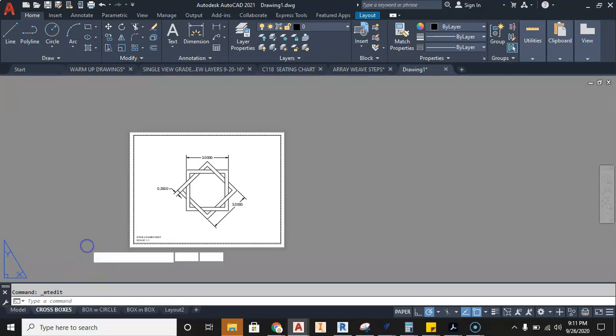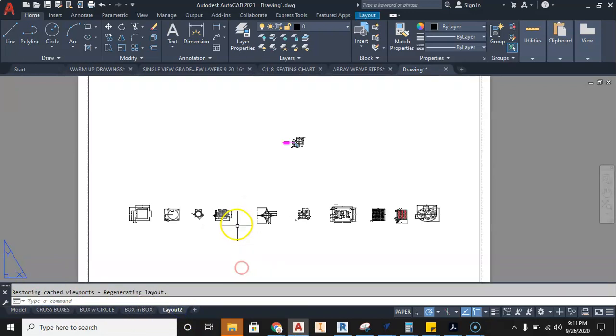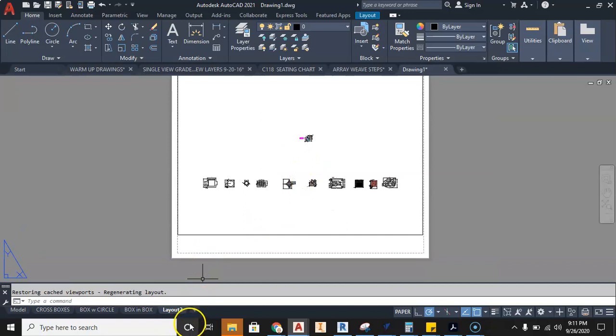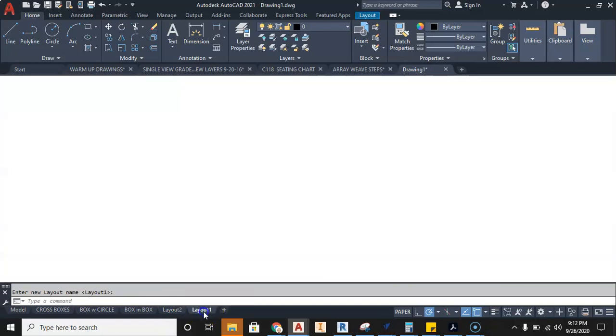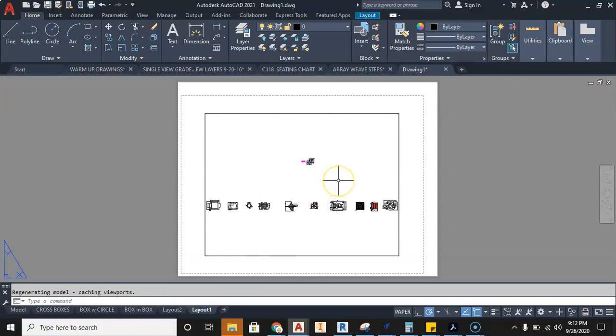All right, so I think you get the hang of this. Just keep working your way down this process. Now, you don't have to make the copies if you don't want to. If you want to go into here, keep laying them out this way, you can. If you need an extra viewport, you can hit this little plus. That little plus makes an extra viewport. But again, it's just a basic viewport.